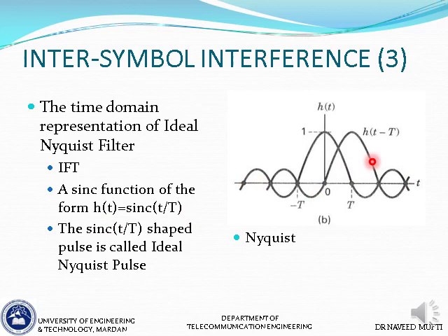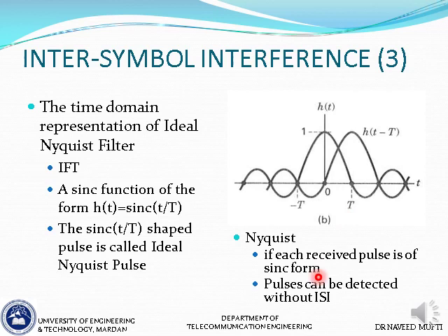So what did Nyquist show? He showed that if each of the received pulses is of the sinc form, so in time domain, if each of the received pulses is made to be of the sinc form, then pulses can be detected without ISI.